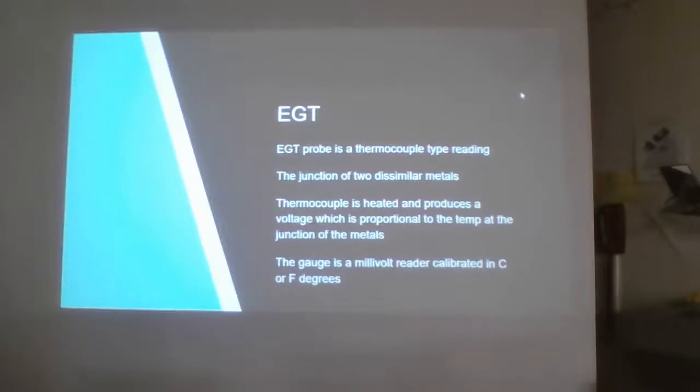You'll see when we measure these probes, what's typically called out for in the manuals is a megger or a millivolt reader in order to test these thermocouple probes to make sure that they're in the correct operating range. I've seen a lot of thermocouple probes that won't read at all. Usually, if there's something wrong with it, they'll call it a dead thermocouple because it won't read the certain voltage. It'll read too low, and that's when you know that it needs to be changed out.